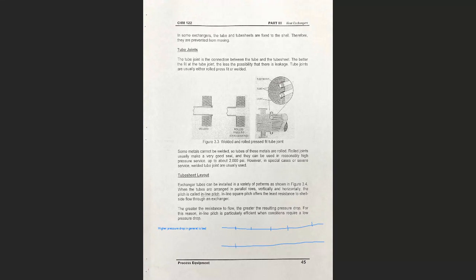Instead of 5 pumps you will only need 3, because the pressure here is not dropping as fast compared to the system above. That's why in the second example, a process with much lower pressure drop, the number of pumps you need will be much smaller.